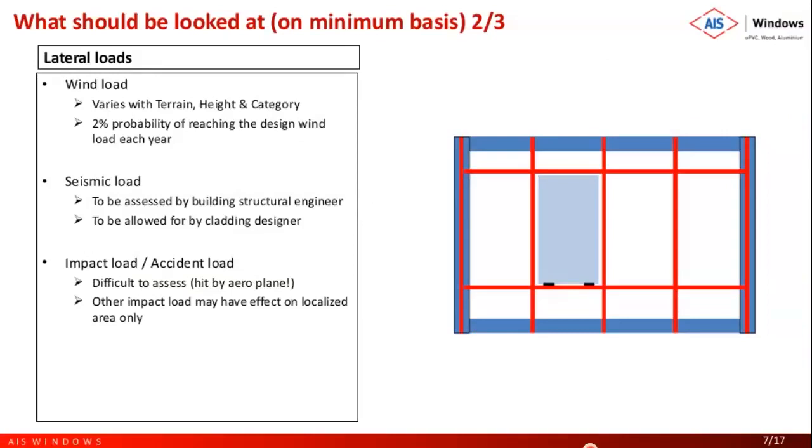Here what we need to note is there is only a 2% probability of reaching the design wind load each year, and that 2% is actually statistically related to the 50 years design life. So next is the seismic load.